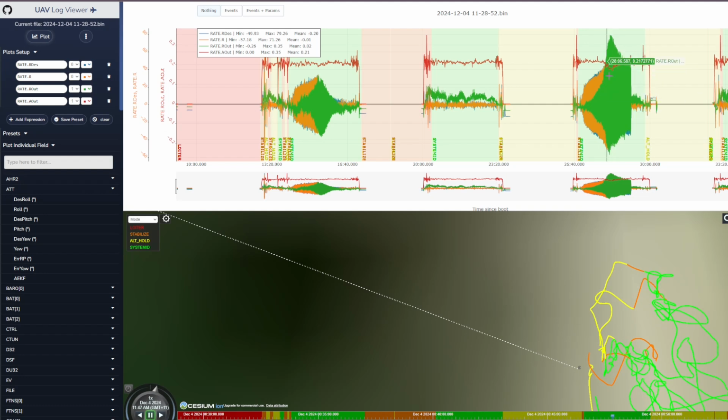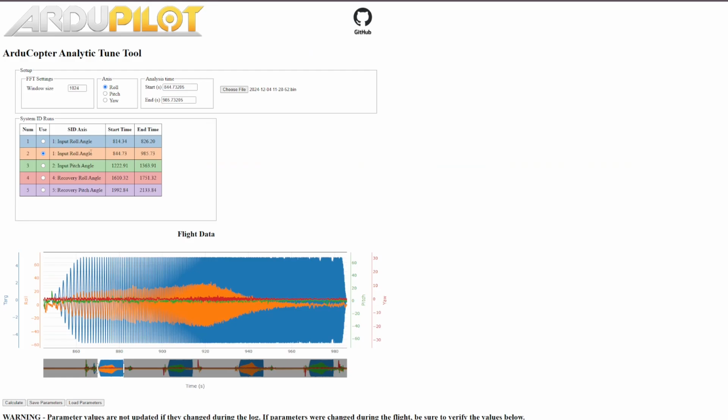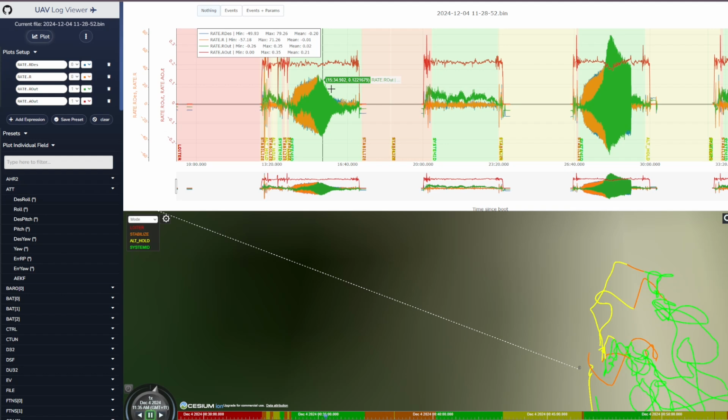Anytime you see this, you're going to want to reduce your maximum lean angle to ensure this doesn't happen. So to do it with the recovery roll, I'll probably need about half what I've asked for here, because you can see the input roll goes through the command model, and that smooths everything out a little bit, and reduces the magnitude of the frequency response, especially at the higher frequencies.